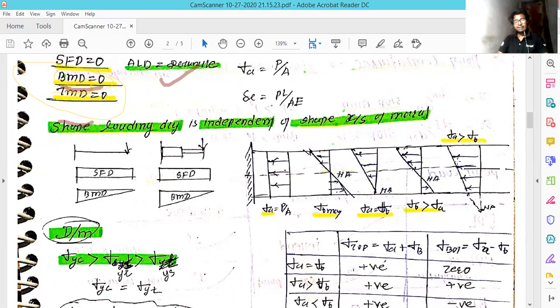Now we see an eccentric kind of force, in which axial force is there and it also produces bending stresses. In this condition, the top portion will be under very high compressive stress, or it might be in tensile stress, and it will be zero at the bottom most section. Moving from one section to another, the bending stress is higher compared to the axial stress. Due to that, the neutral axis will be shifted toward the bottom side, because in bending the most tensile stress will be developed at the top most section and the compressive stress at the bottom section. So when these two effects get combined together, the neutral axis is shifted towards the bottom most section.